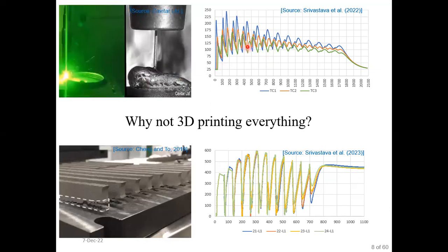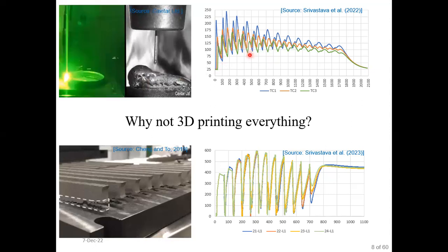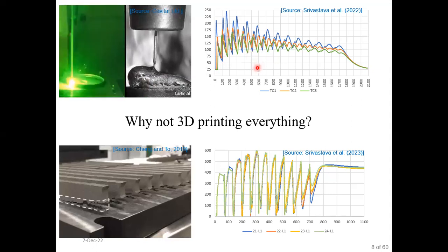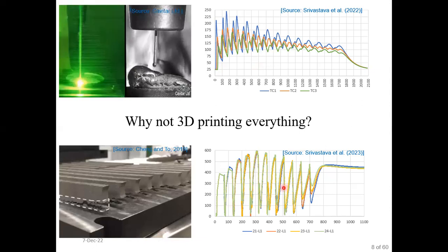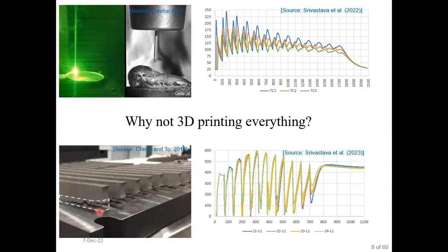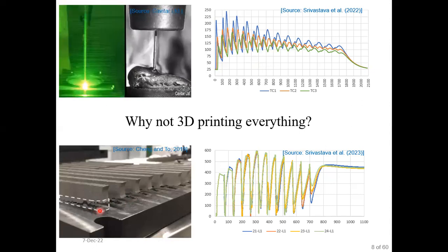However, this dramatic rise of temperature causes severe consequences. The consequences are in the form of residual stress and distortion produced in the component. Because of the residual stress produced in the component, we can see that the component got delaminated from the substrate before it goes to the application. And because of that, this part qualifies as a failed product and it cannot be further utilized.